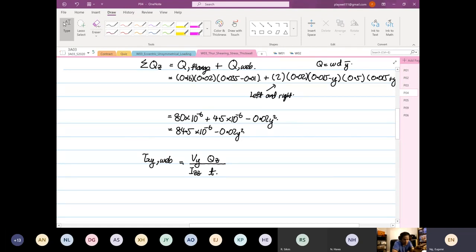Izz is also going to be constant. There you go. Izz is also a constant. Some of you like, oh no, but Eugene, you just drew the shear force, it split. Yes, it did split, but you still write it out as a constant. Later on, you'll compensate elsewhere. I'll tell you where. So Vy now is equal to 90 times 10 to the power 3,